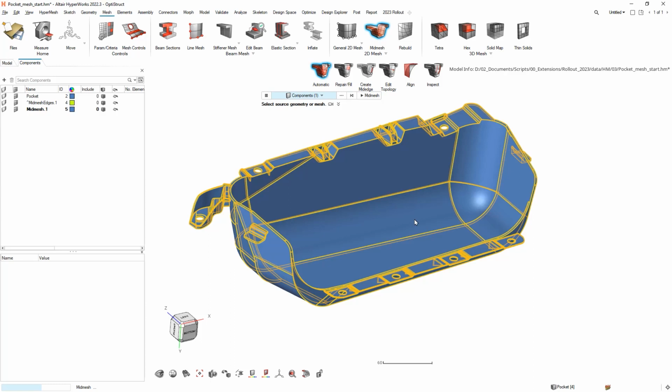So if I split the CAD surface, the FE geometry will follow it. And also mesh selections are a lot easier. Selecting by surface becomes inherent in the fact that it exists as both CAD and FE. So I've shown stitch and split, but tools like drag, extend, imprint, and ruled can all be used directly on FE geometry as well.